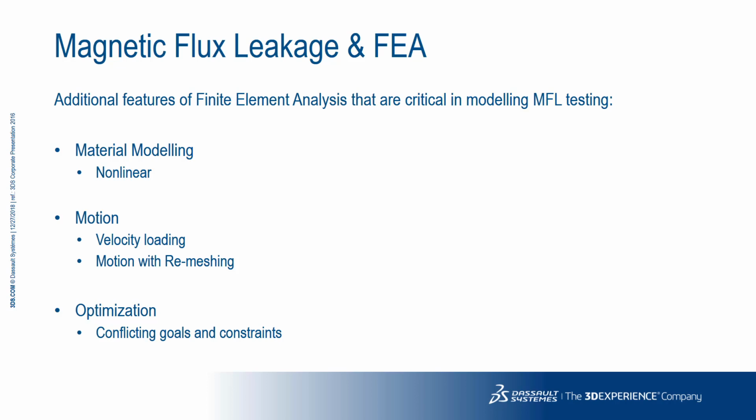Such schemes aim to deduce the shape and dimensions of a flaw from the voltage induced in a pickup coil moving relatively quickly along the structure. MFL simulated with purely a velocity effect gives rise to an additional difficulty in both signal interpretation and modeling due to the formation of eddy currents when an excitation source moves over or inside a metallic pipeline.